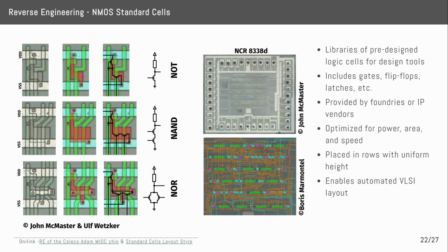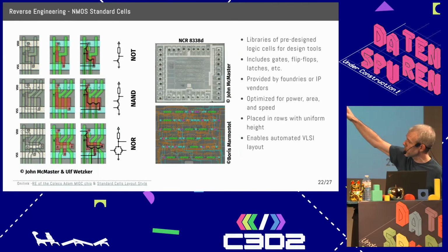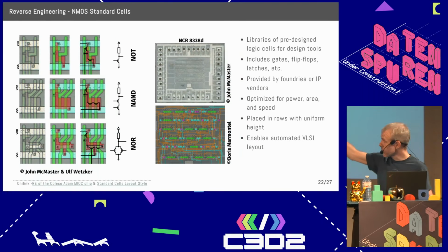And therefore, you can start painting small transistor images on top of these colored areas of your chip. And if you trace the interconnects, you suddenly find out how everything is connected. For an NMOS type of process, you only have NMOS transistors over the whole chip, and therefore you need so-called enhancement and depletion type transistors, which actually form a resistor. So the transistor on top is actually working as a resistor. If you trace this, you can then work out what the logic functions are.